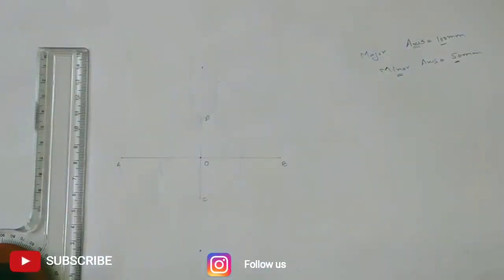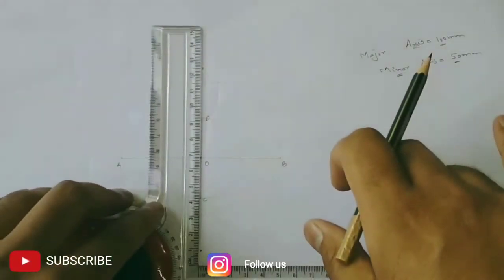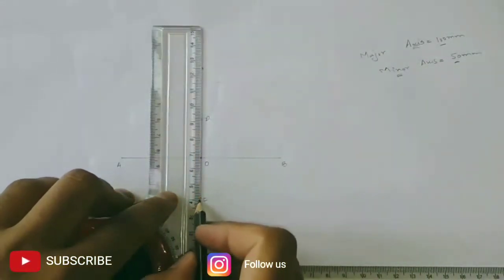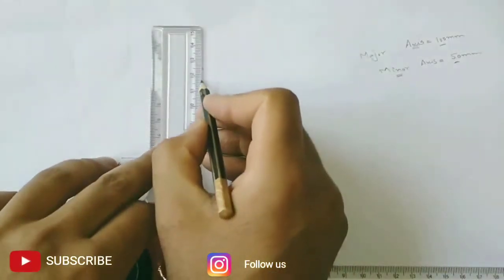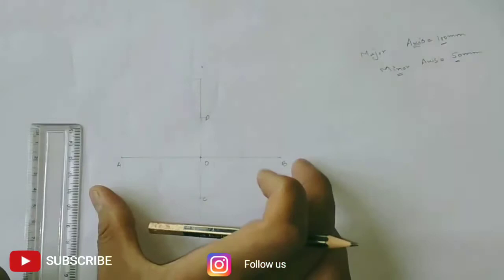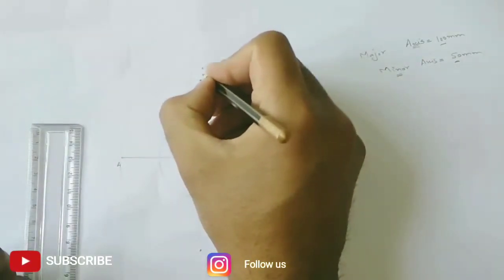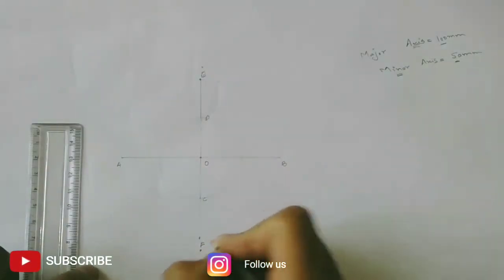Alright, next let me first extend this minor axis CD a bit so that it will also represent the vertical diameter of my larger circle, whose diameter is equal to AB. Let me name this as point E and this as point F.